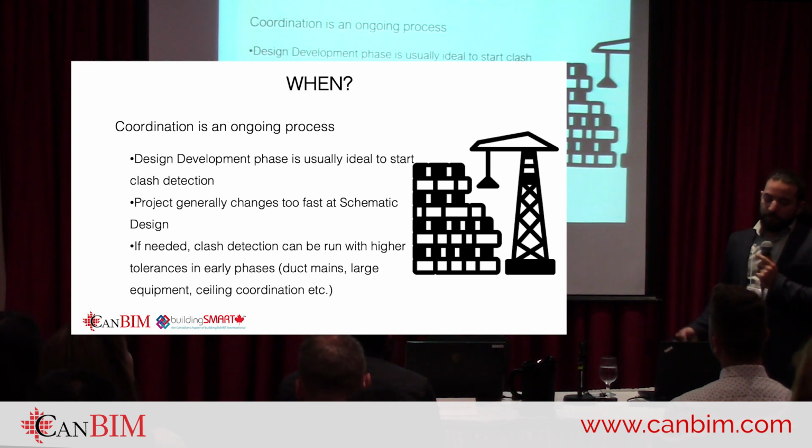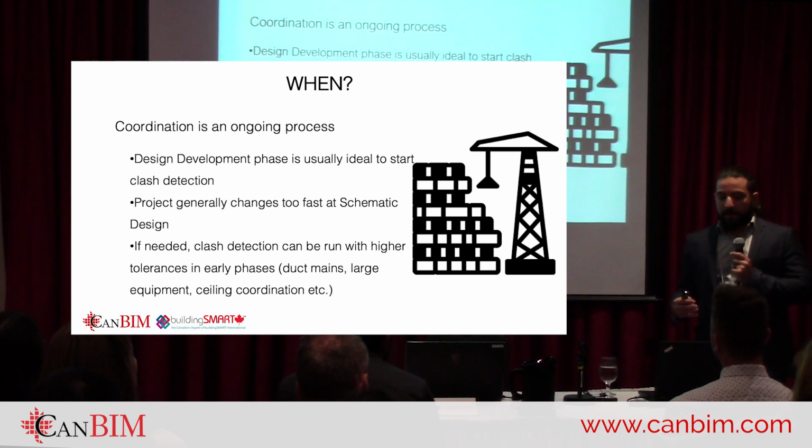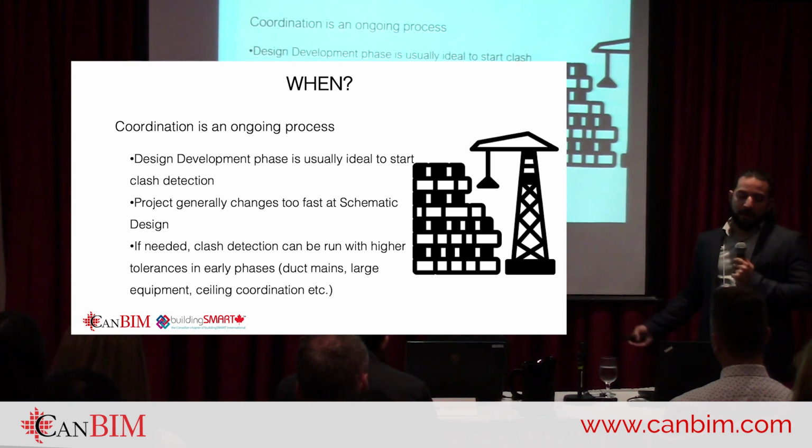So it's not really very useful to do that in that phase. But in design development, you can start doing it and maybe increase the frequency of the clash tests as the project ramps up, and you can do it on a weekly basis when you're in the CD phase.